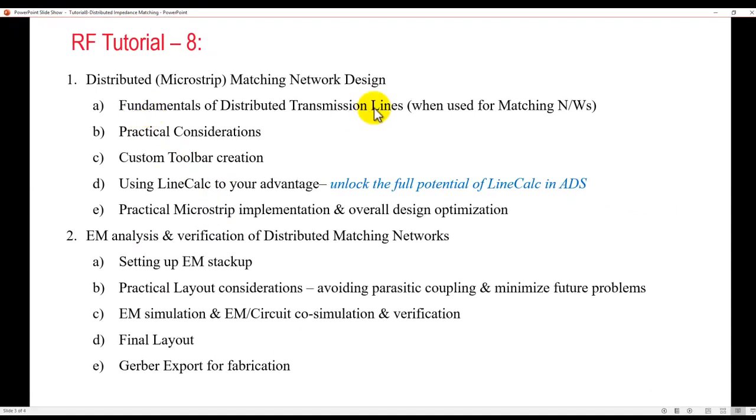To quickly summarize, you need a thinner line to produce a good inductive behavior. It helps you save some design area by having smaller lines. For capacitive action, you can go for wider lines. It will produce more capacitive action. And never cross the minimum and maximum limits of your impedances. Also, while designing this kind of network, always keep in mind what's going to come at port 1, what's going to come at port 2, and have the series lines appropriately connected. Otherwise, you will need to do that very late in your design when you realize something has happened.